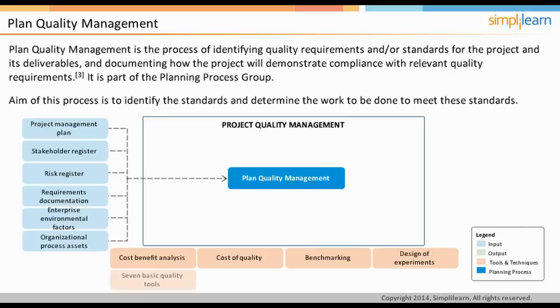In addition, the 7 basic quality tools, also known as the 7 QC tools, are used to determine the plan to achieve the desired level of quality. Statistical sampling as a tool becomes relevant whenever the quality plan cannot be applied to all the artifacts produced. For example, if destructive testing is a requirement, then it can be carried out only on a sample, not on the entire population. Statistical sampling helps in arriving at a representative sample that can give useful information.